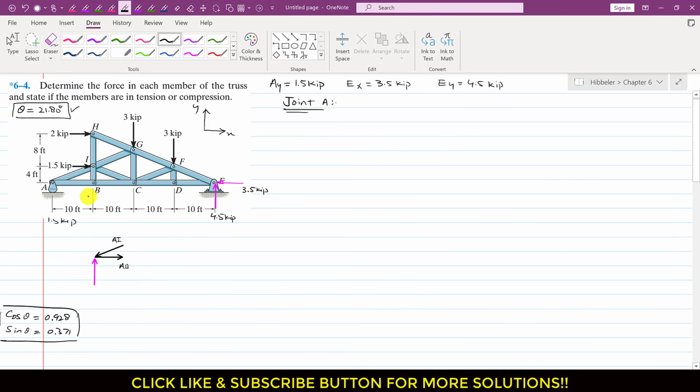Here we have that same theta, and here as well. So this is the free body diagram for joint A. Now to find this AB and AI member force, we need to resolve the AI member force into its components. It will have one component acting downwards, and one component acting in this direction. And this is that AY force, which is 1.5 kips.